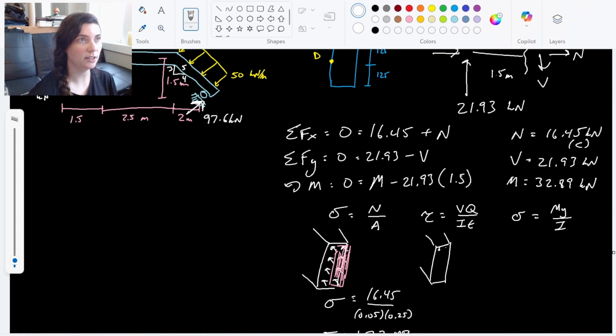Right, so there's little shear, and there's more shear, and there's a lot of shear in the middle, and then it goes down again to nothing at the edges. So it looks something more like a parabola, a parabola of stress in that cross section.